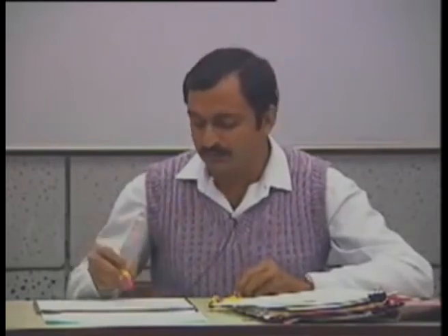Sometimes what I have also done is that the equation of all the surfaces is stored, and then when you need the Octree model, you generate the Octree model immediately, so that you don't lose the geometric information also. In that case, you are using a combination of two, some kind of a boundary representation plus an Octree. Octree used only when you need the Octree representation.